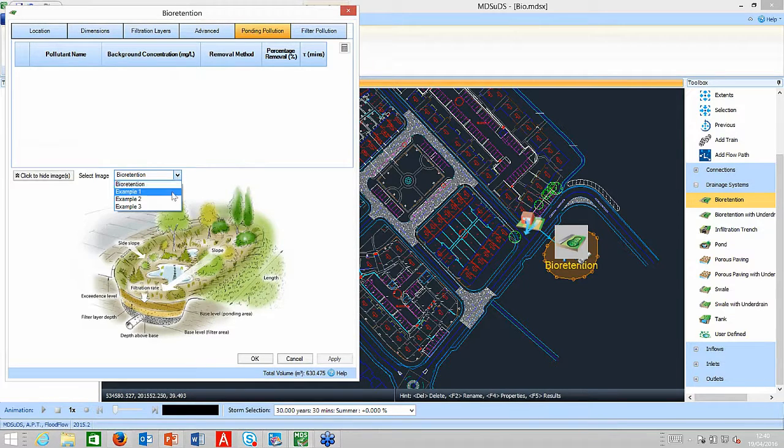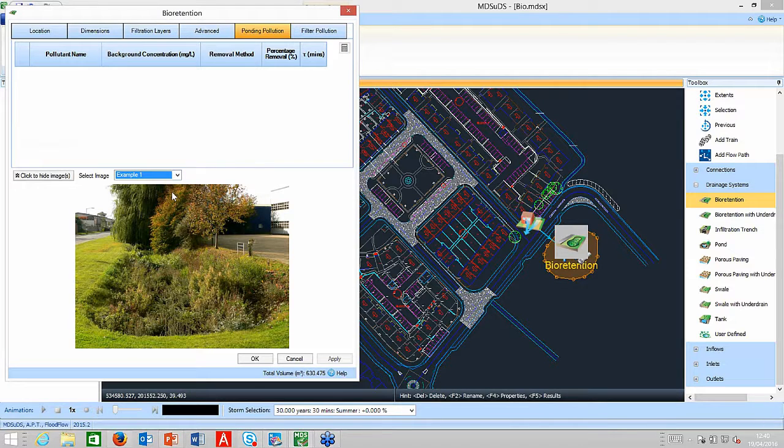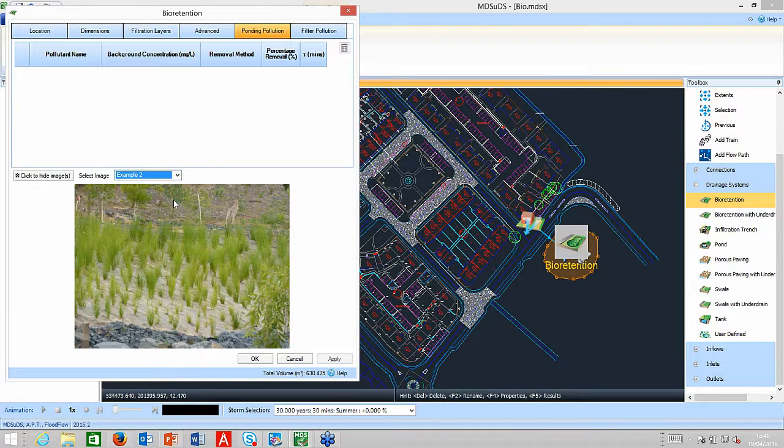Have a look at a few more examples of what I'm talking about on a local scale. They can be these kind of things between the highway and an industrial development. So anyone working on commercial premises, industrial sites, business parks, things like that, often you'll see landscaped areas like this, and they will have a bioretention filter media down below them. So they're multiple benefit, multiple purpose structures.